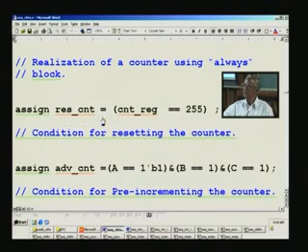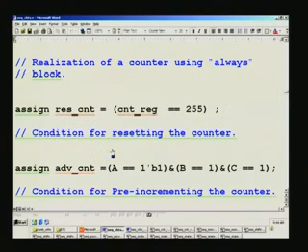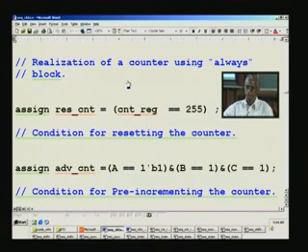A typical thing you can take is some 40 megahertz or 50 megahertz on Xilinx and even Altera chips. Because at this stage I wouldn't have decided the device, isn't it? Yeah, we haven't. So 40 megahertz or 50 megahertz is only an assumption based upon our prior experience. I have just put 50 megahertz, 20 nanosecond is the time period. So that works out to be 1000 by 20. Always divide 1000 by 20, you will straight away get it in megahertz, so that works out to be 50. So 50 megahertz is a typical value on an FPGA, and that's the reason why I stuck to that.